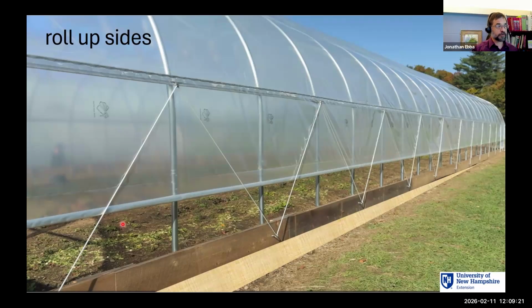We're seeing more and more screening against pests. Of course, if you're screening any of your open spaces, we're going to look at this passive ventilation based upon the open area. And it's just important to note that when we're screening, we're drastically reducing the amount of area that's open. So if you put maybe, let's say, chicken wire on here to keep out woodchucks, I'm totally making these numbers up, we might be decreasing our airflow by 5%, right? But if you put up like a window screen to keep out, I don't know, plant bugs, we might be dropping the area by maybe 50% or more.